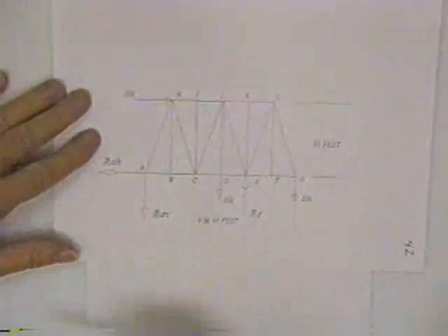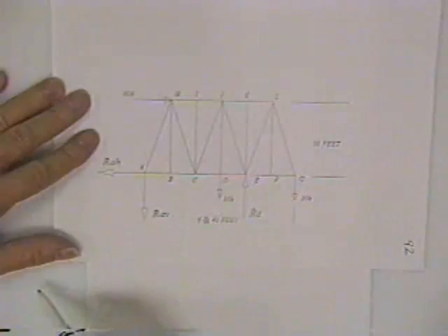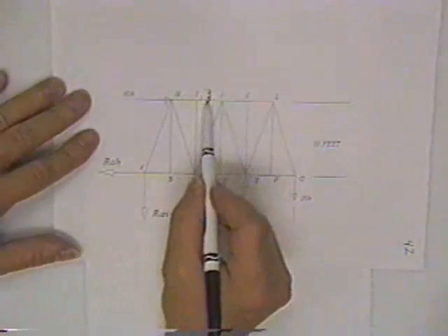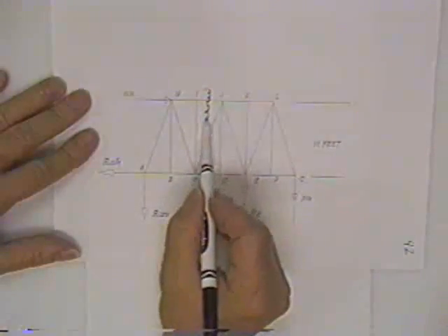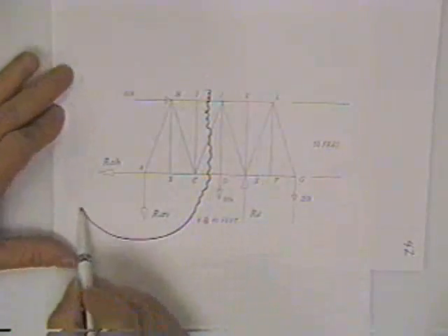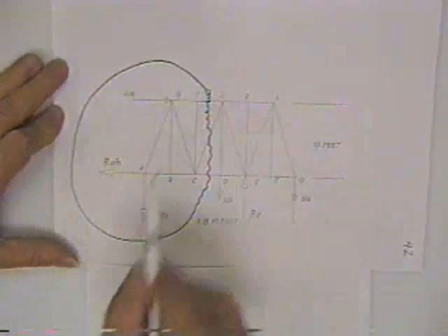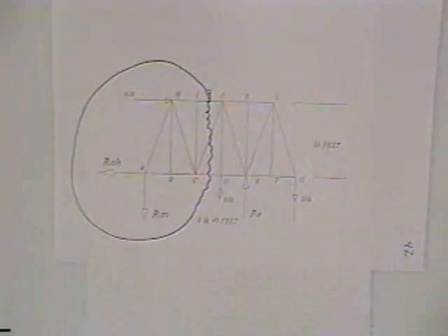All right, now, to solve for the force in member IJ, you must cut member IJ. Then, cutting as few members as possible, you would come on down like this, circle either end of the structure, and that would be your free body.